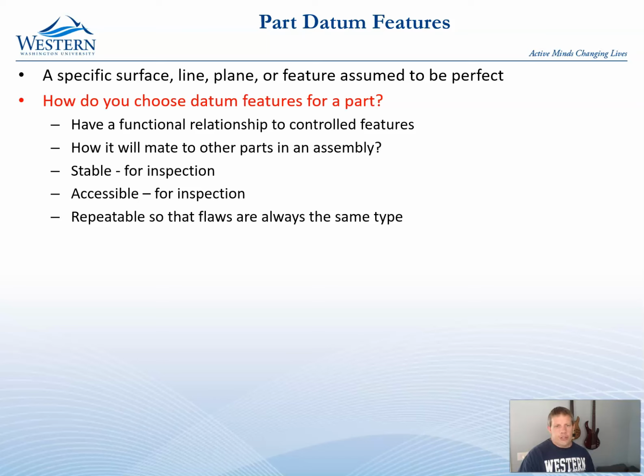So the datum features, how they will mate to other parts in the assembly, is really important. If two pieces are going to go together, then you might make one of those planes be a datum. If there's an edge that things fit together along, you might make that be the datum. Holes, the axes of holes are often used.